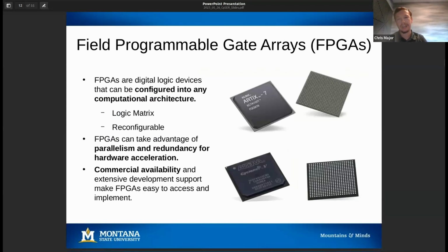So one such technology that would allow for trying to create new types of hardware where we have flexibility in obfuscation is a field programmable gate array, or an FPGA. So FPGAs, just for those who are unaware, are digital logic devices that can be configured into any sort of computational architecture. So imagine a large logic matrix with literally millions upon millions of logic blocks.